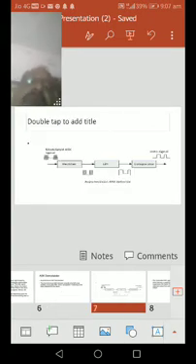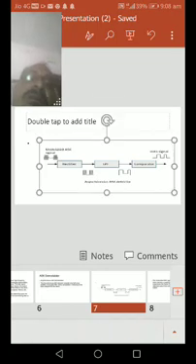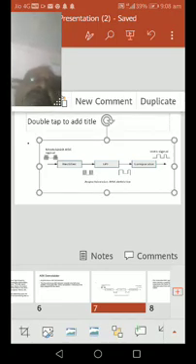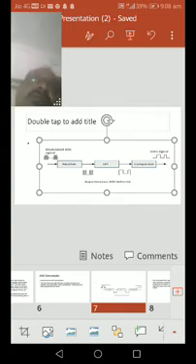For a 1, the rectifier diode receives the positive voltage, so it is forward biased and acts as a short circuit, and the signal passes through. The output is given to the low pass filter. If the input is 0, the diode is reverse biased and acts as an open circuit.